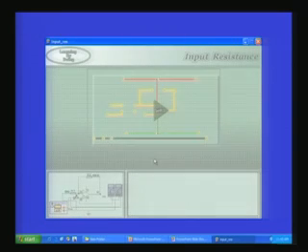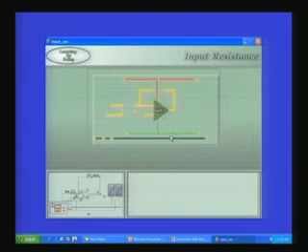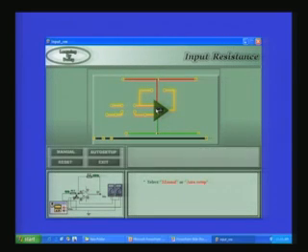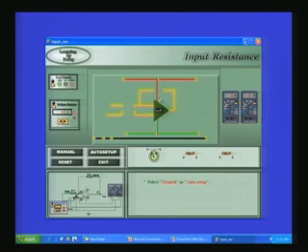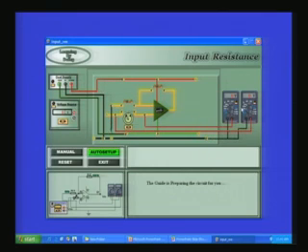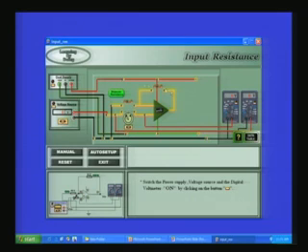So you have here a board in which the op amp is sitting at the center. You can see the op amp. This is a printed circuit board in which the op amp is there, and you have some gaps which you can fill, and I will now do auto setup, so that you can see I have put a variable resistor here, I have put a fixed resistor here, R1, this is R2, and the wiring is completed by using two multimeters and a dual supply and a voltage source, etc.